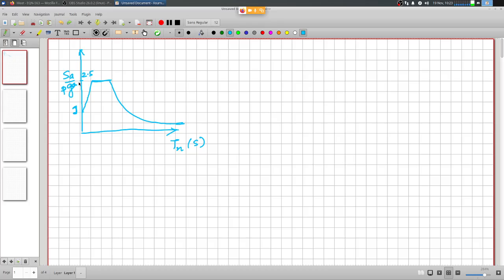So the 0 period acceleration, that is the peak ground acceleration of the ground motion, is anchored to unit value. And of course there are two sets of design spectra that are specified. One is, if you will see, this linear portion is replaced by a constant flat line, right?